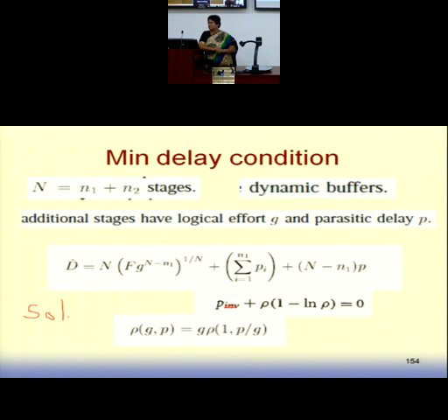So I think we need one more class, and then we will finish up with the logical effort concepts. We have more or less discussed everything related to synchronous system design. We have seen how to design a flip-flop, how to design a synchronizer, how to design a clock distribution network, how to design a PLL, how to design or minimize a combinational logic block using logical effort concepts, including the power estimation concepts also.